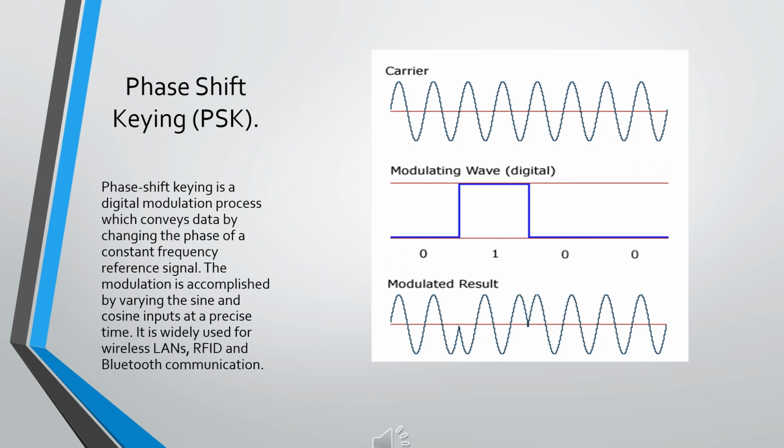Phase shift keying is a modulation technique used by modems in which different phase angles in the carrier signal are used to represent the binary states of 0 and 1. The digital signal is broken up according to time into binary digits, and the state 0 or 1 of each bit is determined according to the state of the bit that preceded it.